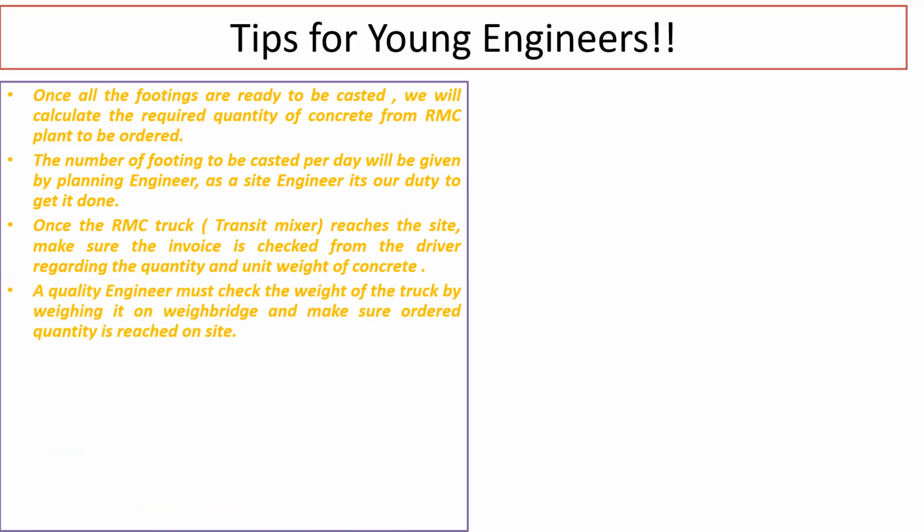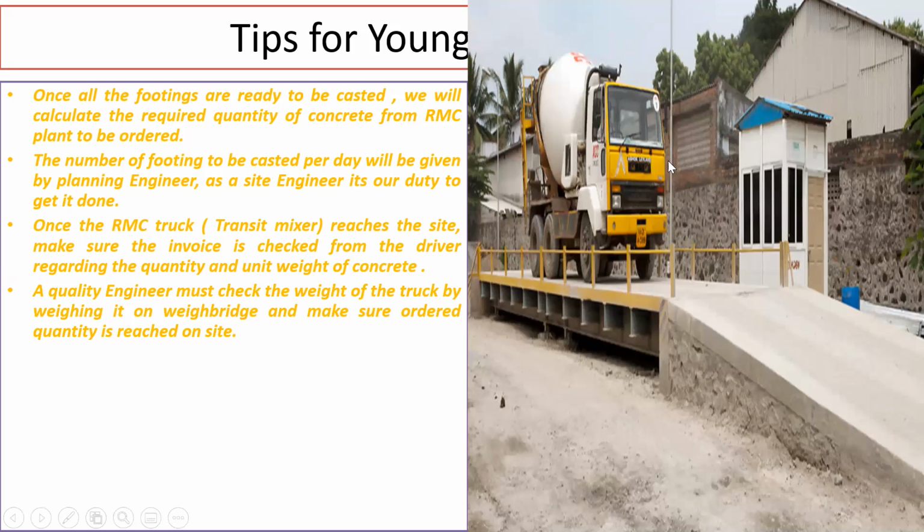A quality engineer must check the weight of the truck by weighing it on the weigh bridge and make sure the ordered quantity has reached the site. When you work in big projects, as I mentioned, you'll have an engineer called a quality engineer, who will be checking all these things, the weight of the concrete that is arriving at the site. So this is how it is.